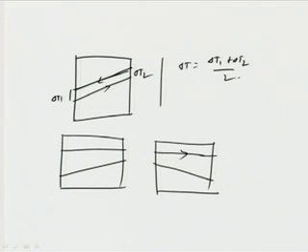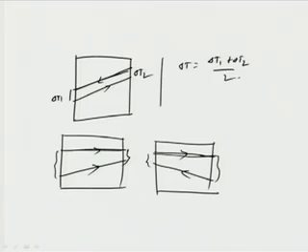So if I say this is the condensing steam, in both cases delta T remains the same, because this is becoming the reference frame, and the reference frame is stagnant. There is no change in the reference frame. Therefore, whether it is counter or co-current, that does not create any differences.